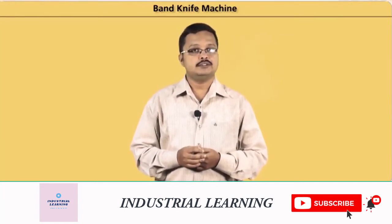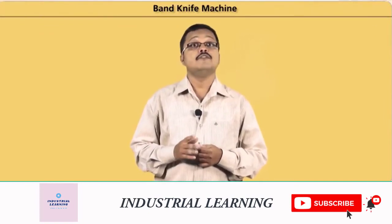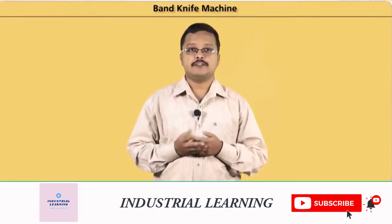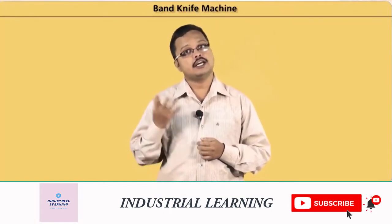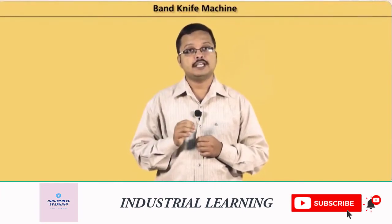Another advantage over the straight knife is that the blade of the straight knife tends to wear out faster at its lower end, which is more in contact with the fabric unless the spread is high enough. On the other hand, in the band knife, the blade wears evenly due to its action cycle.